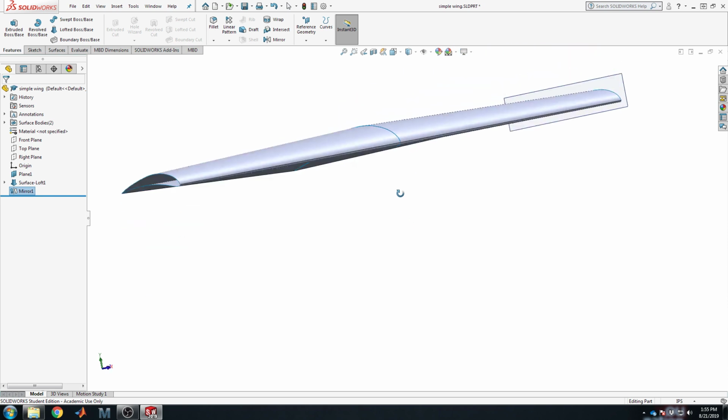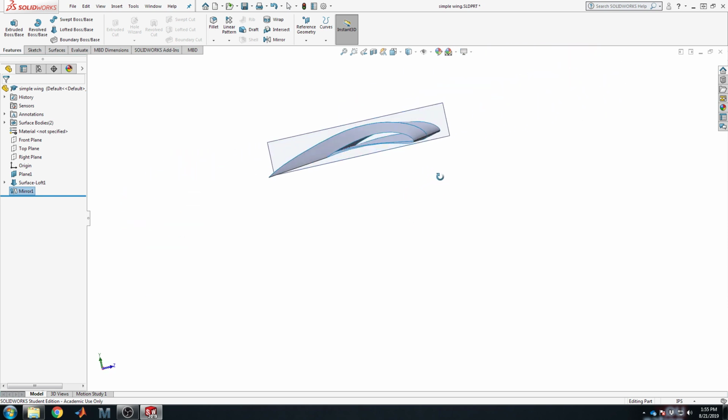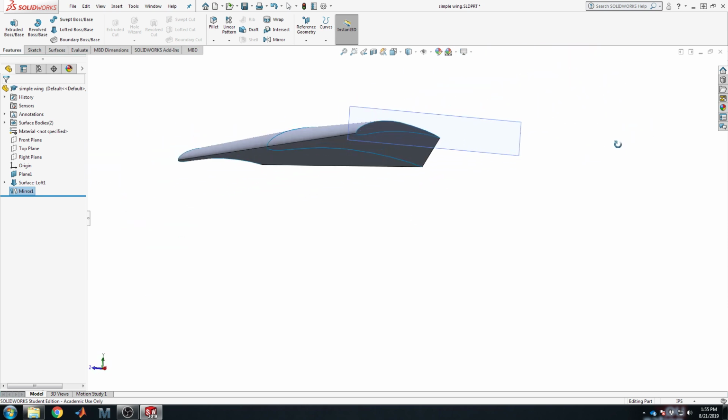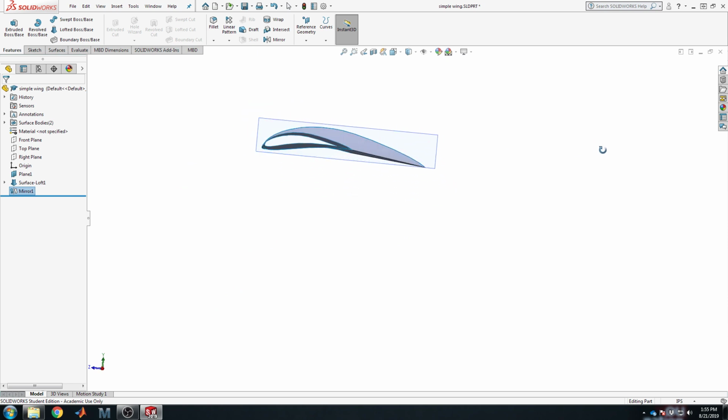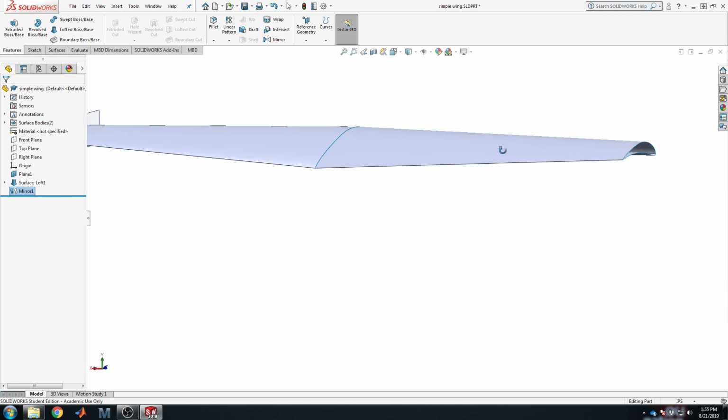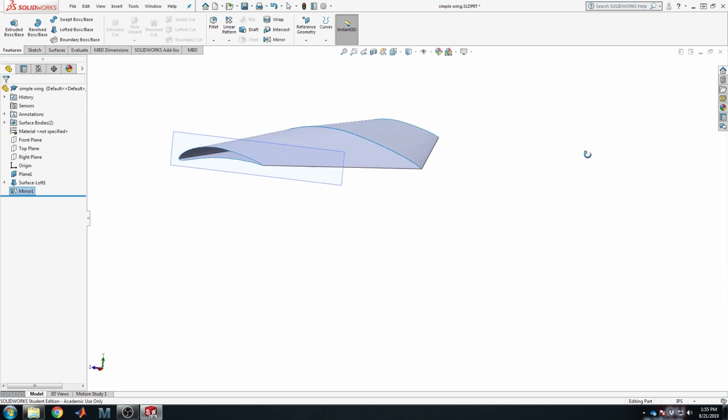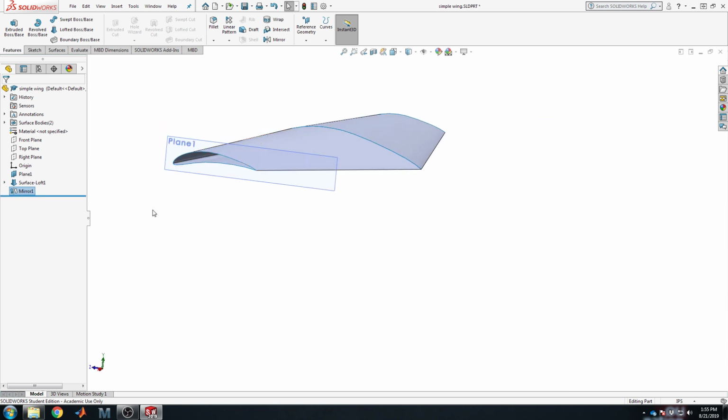Now this is kind of odd. It's a forward swept, extremely high camber wing with slight washout. And that wing is unusual. Probably doesn't make much actual aerodynamic sense. Zero dihedral, yeah. By the way, to add dihedral, let's show you how you would go about that.